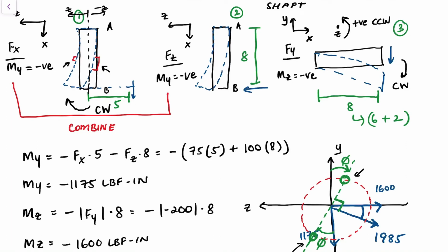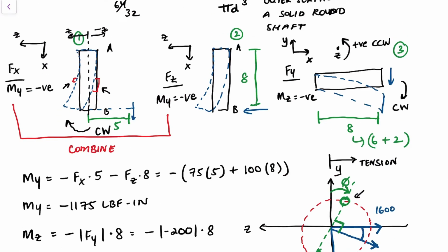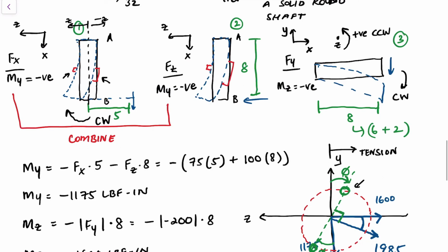So the axial stress is in tension, so we know that we're only interested in the points that are in tension. So based on Fx, everything here is in tension, in the negative z. If we look at case 2, same thing happens. Positive z values are in compression, negative z values are in tension. So again, tension here due to Fx and Fc.